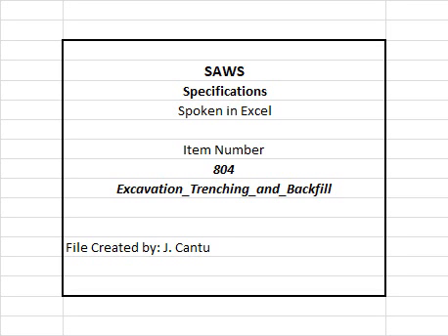804.3 Submittals. All submittals shall be in accordance with engineers' requirements. All submittals shall be approved by the owner's representative prior to delivery of materials and commencing any portion of the proposed scope of work. 1. Contractor to submit cut sheets when applicable. A. No trenching will commence until cut sheets have been approved by SAWS representative. B. The depths of cuts indicated on the cut sheet are from the center line hub elevation to the invert of the pipe.